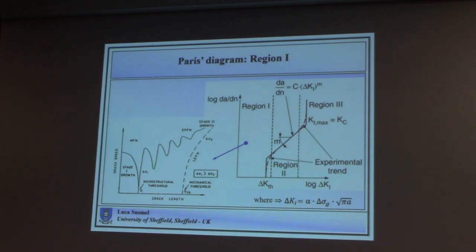And again, if we keep putting energy into the system, at a certain point our crack will be able to break through the grain boundary, running again very quickly through the grain and stopping again. But you see this zigzag path, and so we have a crack propagation. So again, it's consistent with the fact that dA over dN here in this diagram cannot be 0. But it's so affected by the material morphology that fracture mechanics as we know it is not a good theory to model it.